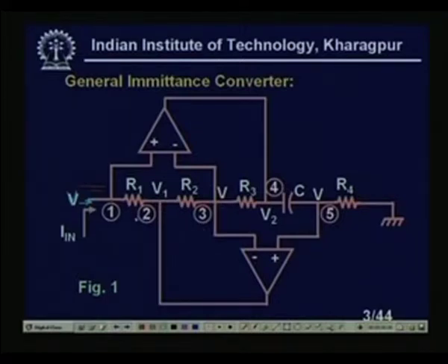We will apply Kirchhoff's voltage law. Now, one thing is very common: this op amp has very high input impedance, so the potential at node 1 and the potential at node 3 are the same. Again, since this op amp, node 3 is common, you see here.